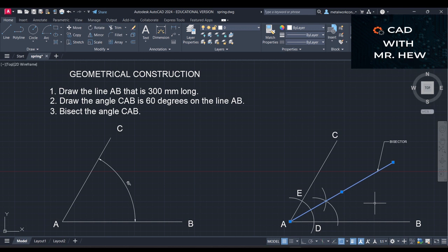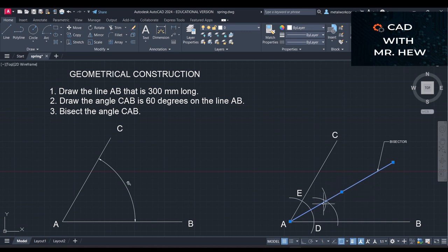This is a bisector, and as I said, this principle can be used in mathematics, technical drawing, and engineering graphics. If you are doing a forces diagram, and you're solving the forces using instruments such as a compass, ruler, and set square, such as in a physics class, this is how you would bisect an angle. If you have a force being applied at 30 degrees to the horizontal line AB, representing maybe a beam in the roof, then this is how you would get your 30-degree angle.